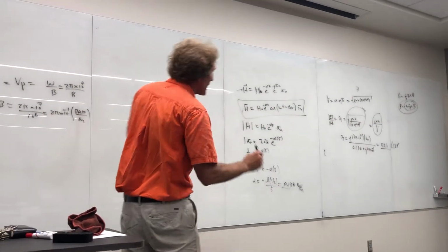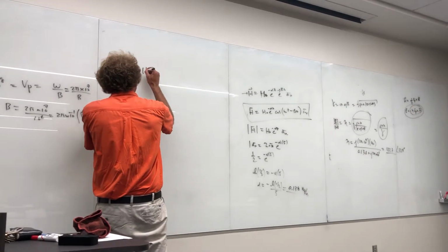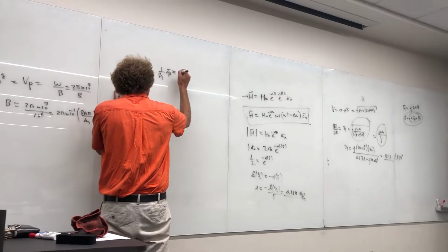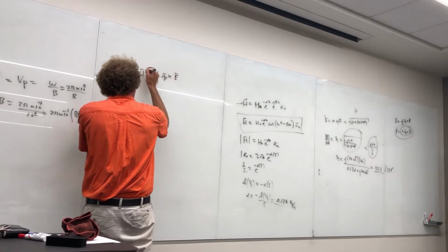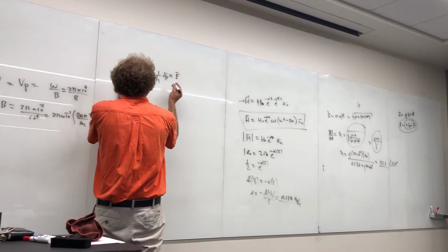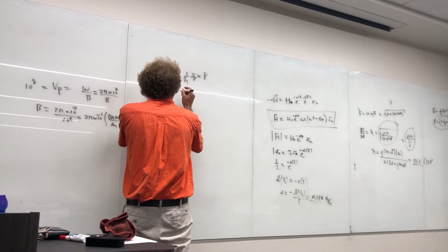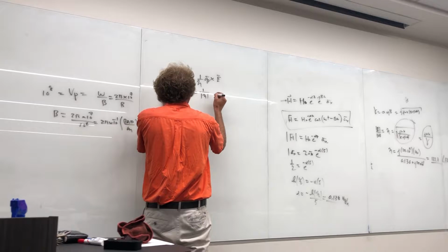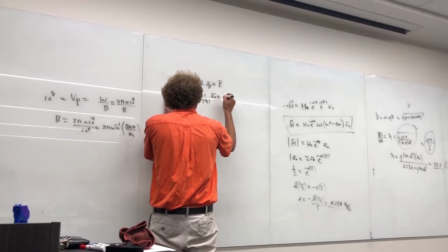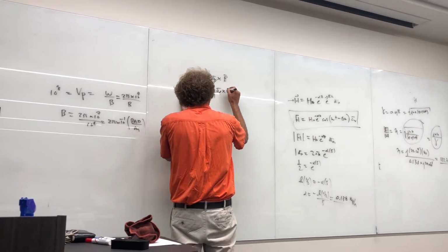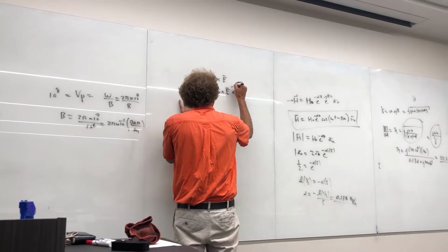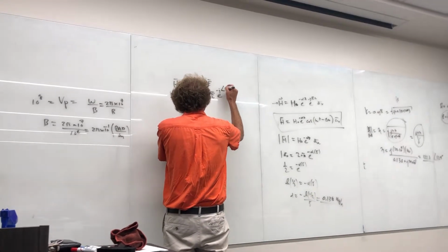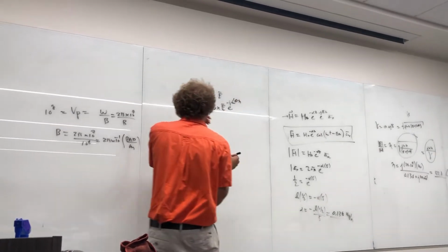Since we have H is equal to 1 over eta, a rho, crossed into E here, I know if I take this and I do this, this would be equal to 1 over magnitude of eta, a rho, crossed into the E field, but then there would be e to the minus j phase of eta up here.